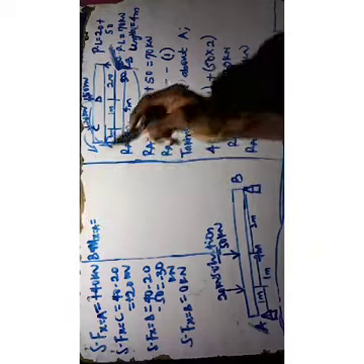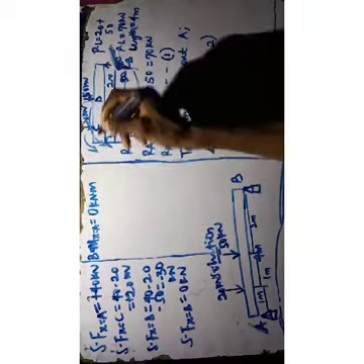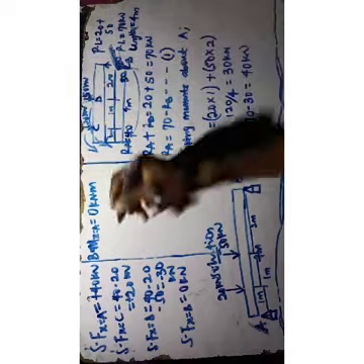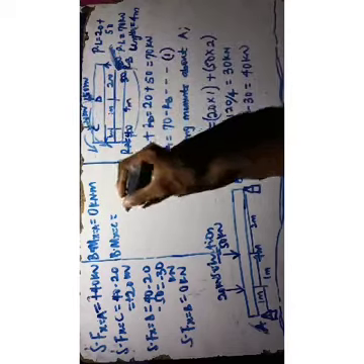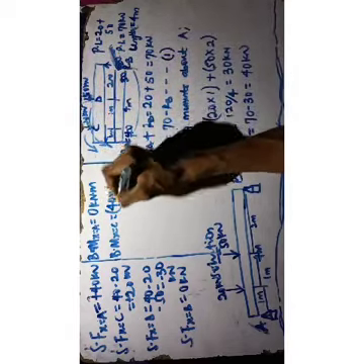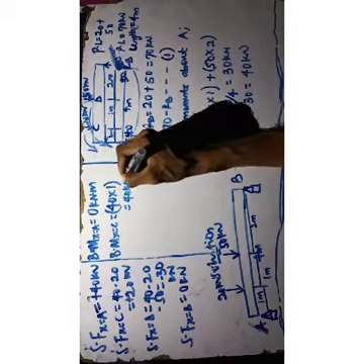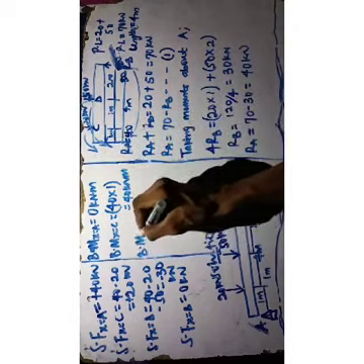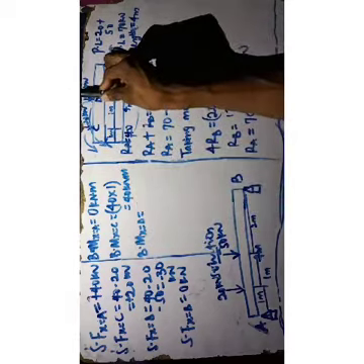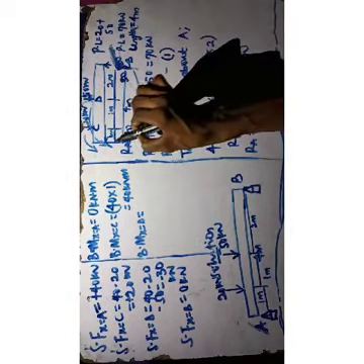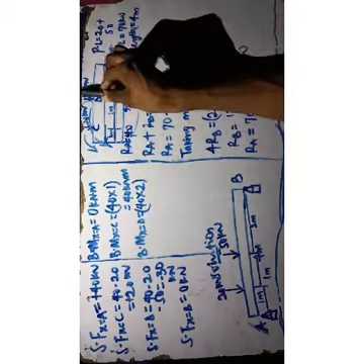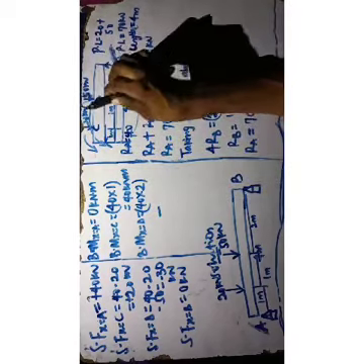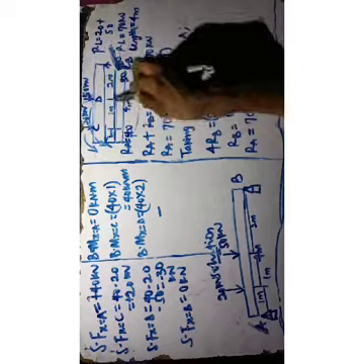Okay. Then now, considering the bending moment at x equal to A will be equal to 0. I told you earlier, right? There's no force here. It's just 40 times 0. So the bending moment at x equal to C, what if I say at C? That means if I cut this part away, that will be 40 times 1, that will be equal to 40 kilonewton meter. The bending moment at x equal to D, if I cut here, 40 is covering how many distance? 2 distance. That will be 40 times 2, minus 20 is covering 1 distance, right? 40 times 2 minus what?